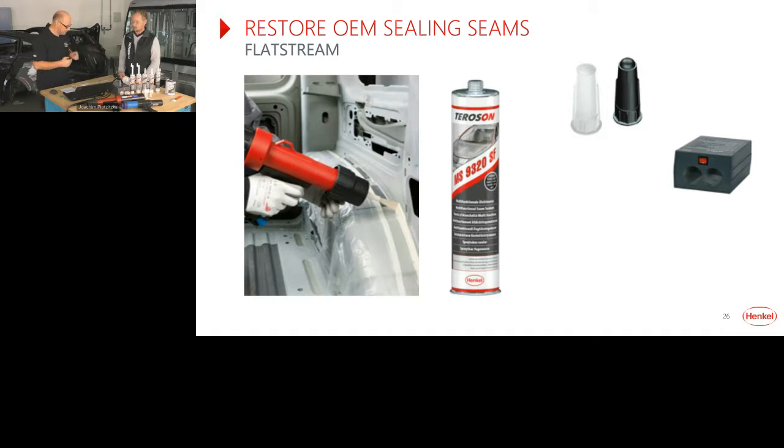Okay. The difference in the appearance of these two is that with both nozzles you can also make small or narrow beads, about 2 centimeters wide, which is very common on a car body. With a FLATSTREAM nozzle, you have ripples that are straight, at a right angle to the line. With the wide stream nozzle, they are more round. So the bead looks like it has round ripples.